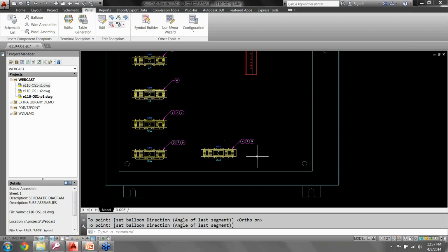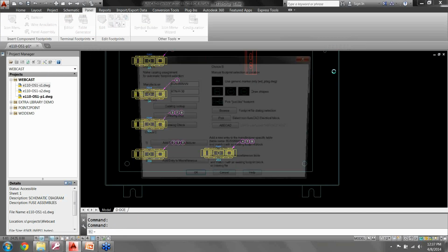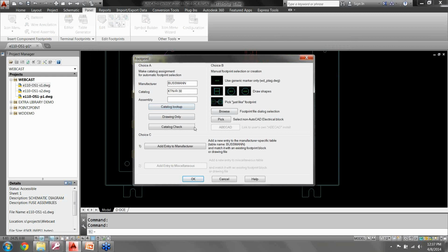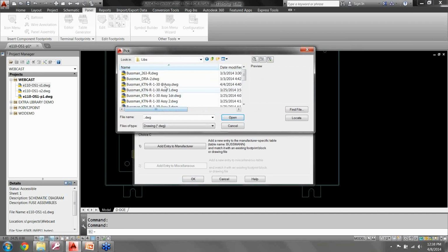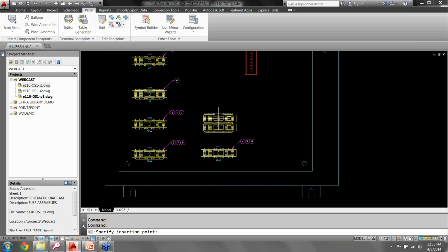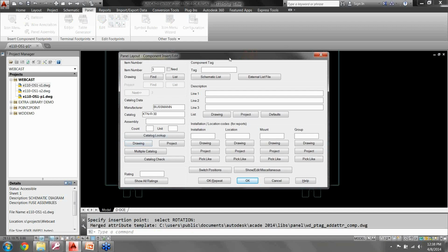Another good advantage though when working with an item such as this, over the assembly code and assembly list version, is I can actually come over here and mix and match these. So for instance, I can take this Bussmann fuse here, and I'm going to keep it on the 31 there, but do the browse, and I'm going to grab the double. So for instance, right here is a Bussmann with assembly of 2. I could not do this with the assembly code and assembly list version, but I can do that with this version to where I connect it up. I can tell it this particular one.